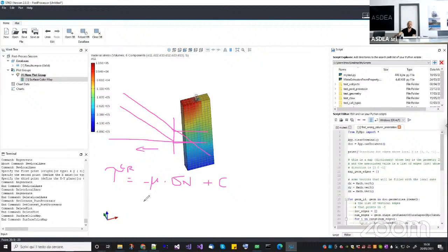So that's why if you turn off friction, setting mu to 0, it's like using this kind of surface. So the cohesion will always be there, because actually the cohesion has nothing to do with friction itself. The cohesion is like an extra shear strength of the medium in between the two contact bodies.